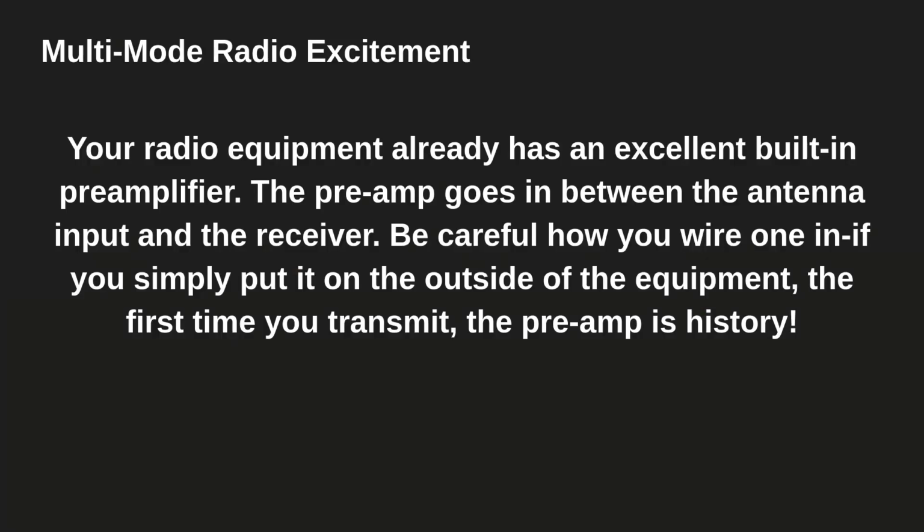Alright, your radio equipment already has an excellent built-in preamplifier. The preamp goes in between the antenna input and the receiver. Now be careful how you wire it if you simply put it on the outside of the equipment. The first time you transmit, the preamp is history.